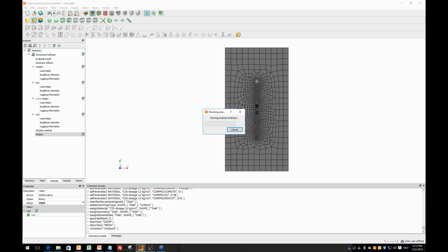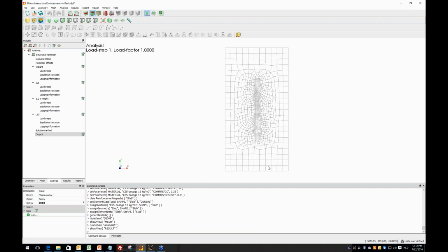So the analysis setup is exactly the same if you want to model the truck in the ULS as well. You have to model also a sheet for the location of the truck, you apply a force on that, and you can use this force also in your analysis.